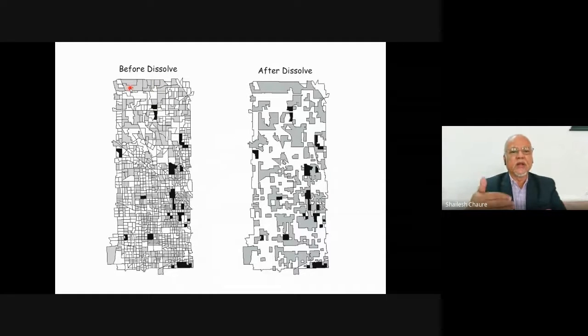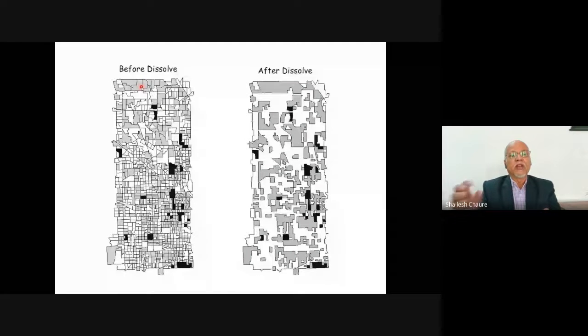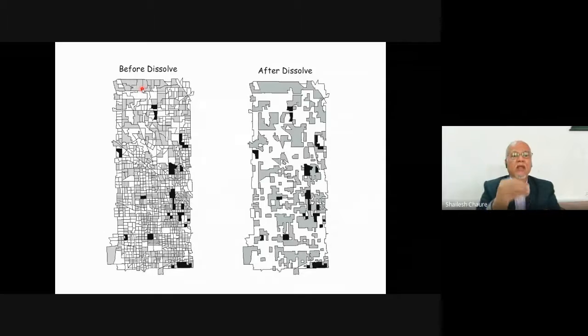It is not conveying the thing very clearly. But if I remove the boundaries between the adjacent polygons which have a similar attribute or property, then it will definitely make a big polygon. So based on some attribute, I can dissolve the boundaries. As a result, I will have this kind of map.